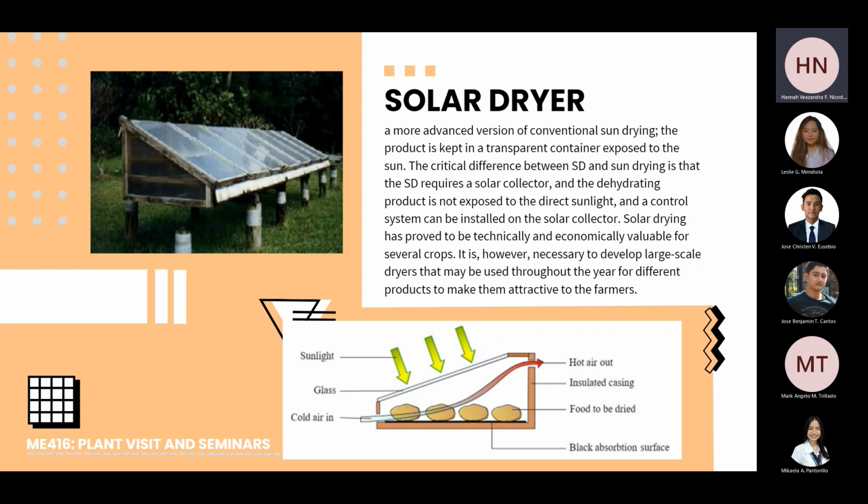The drying chamber could be a cabinet type or a tunnel where air heated by solar energy is blown. The air could be moved by natural draft where a chimney is integrated in the system or circulated with a blower in a suction or forced mode. After drying, the air has become humid and is discharged from the drying chamber. The solar collector unit is very useful for obtaining air with higher temperature. Next po.